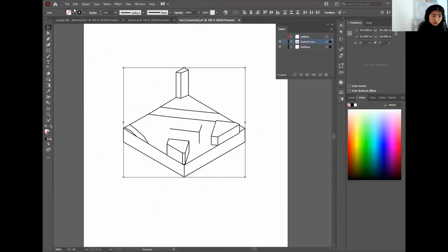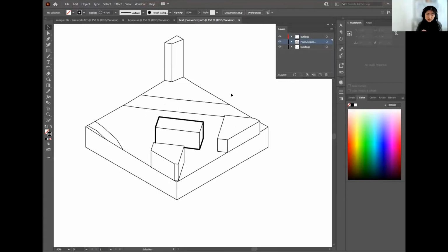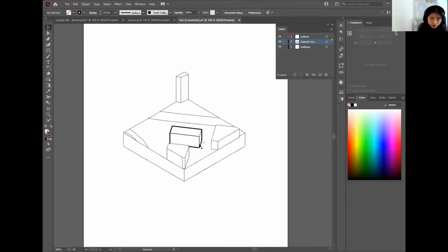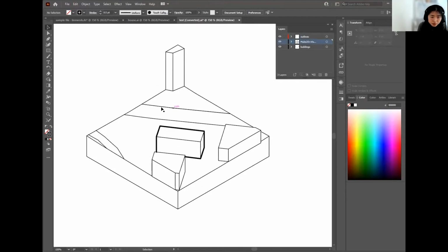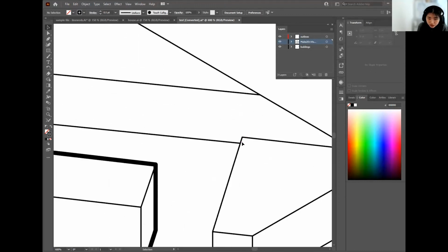If you know that you have specific lines that you know are gonna need to be thicker, you can just change up that line work in Rhino. And I think Rhino is a little better in adding lines and deleting lines. It can be a little bit fiddly in Illustrator. For example, though, I think for regions, especially regions that share an existing line, you might have to duplicate this line and create those outlines in Rhino. So, and you might have to do a bit of splitting and so forth.